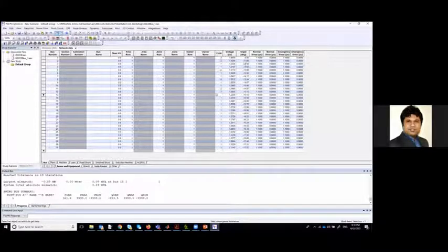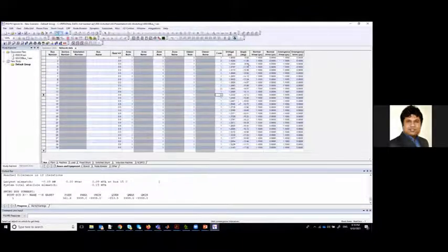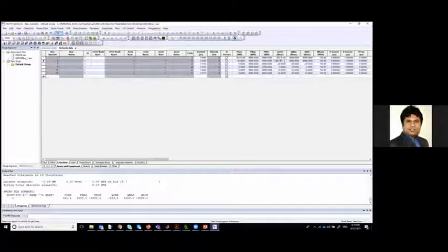So if you go to the plant tab, now this value has changed. If you look, this Q value has changed now, okay? So all these bus voltages and everything has changed, like P, and for example, for this one Q has changed now, Q gen, it was 0 before. That means now we know everything. And now here the infinite bus is supplying power. Look, here it's supplying power because the load demand is high.